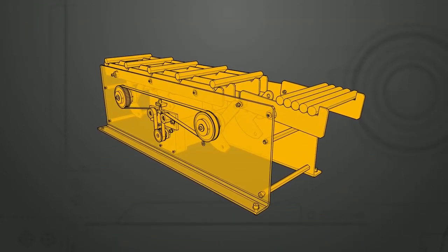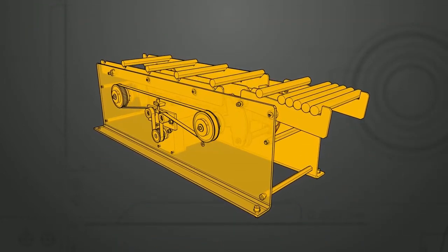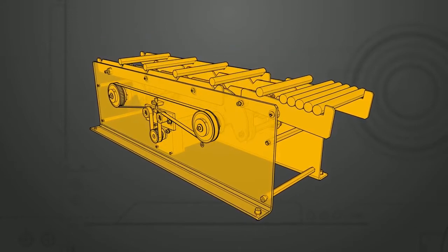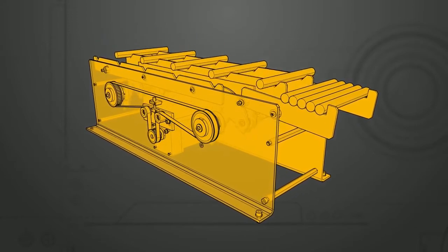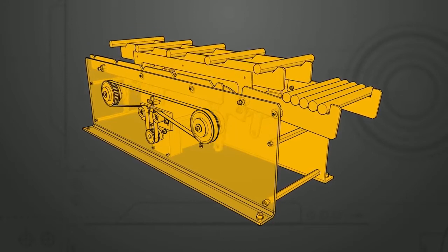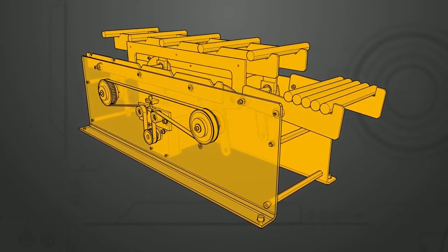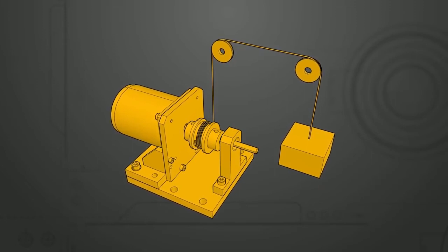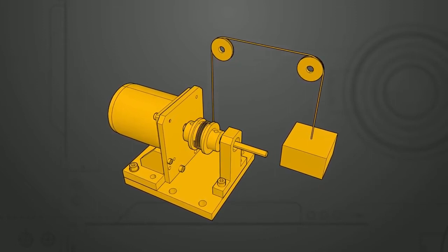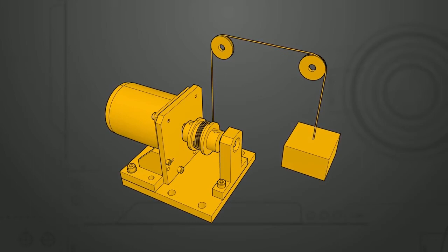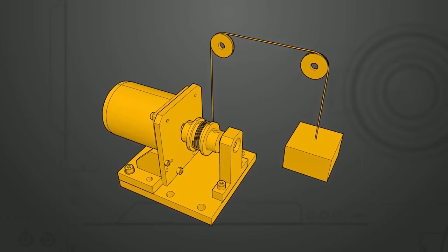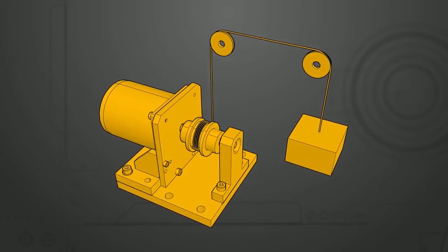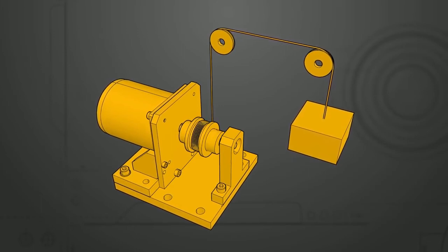In this application, the rotary shafts are used to transmit the torque generated from the motor to the pulleys they are mounted to. The shafts then move the machine's arm to move the rods. Here is an application where a rotary bearing is used on the rotary shaft. The shaft is supported on one side via a support and bearing. It transfers the motor's power to the winding drum, which then lifts the workpiece block.